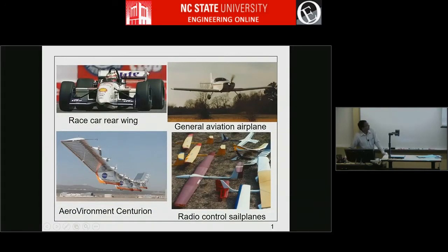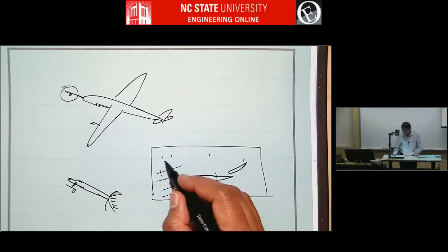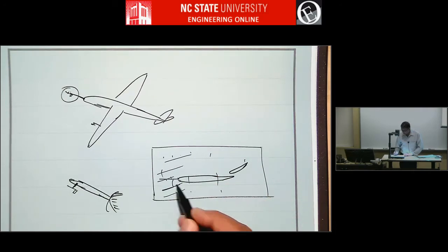You can see here there are end plates, right? These are the sort of plates that cap the wing on both sides, and they help to reduce the trailing vortex effects, so they're always used. So somebody was saying, well, maybe we can do oil flow visualization on this and see how the streak lines are, and that angle will give the angle of attack.